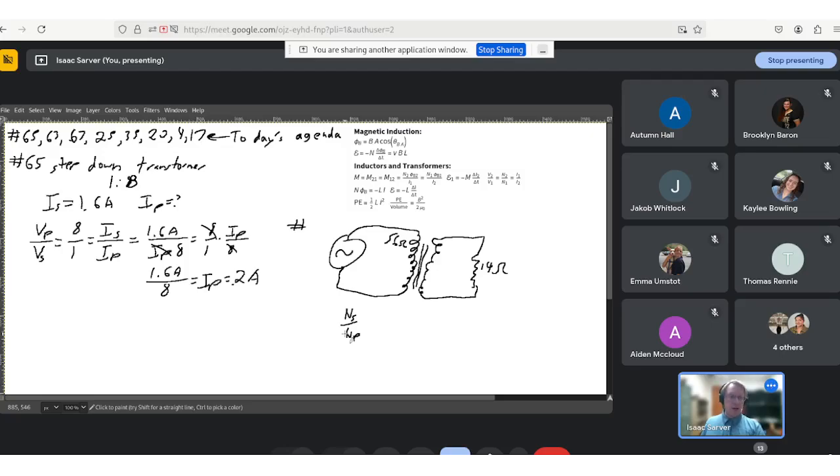So you want to put an 8 ohm speaker on an 8 ohm resistance socket, and 4 ohms on a 4 ohm, and so forth and so on. So if everything goes the way I think it will, what we're actually looking for is power on one side equal to power on the other. Power on the primary, power on the secondary.